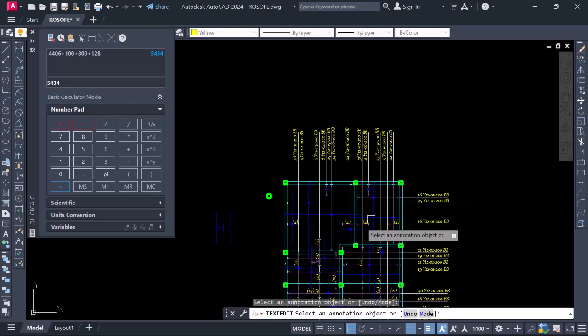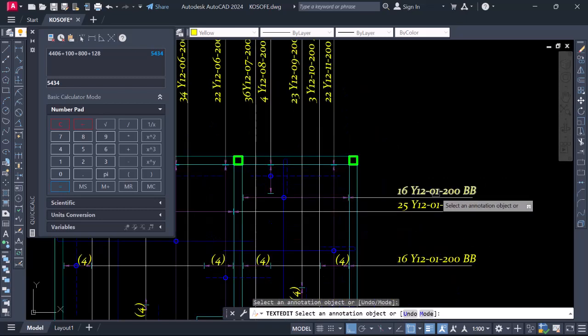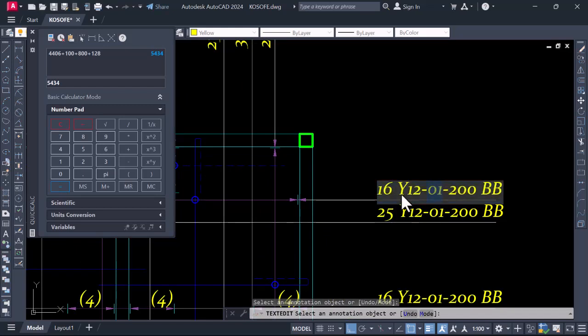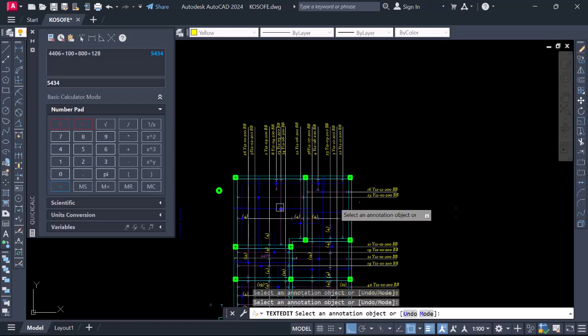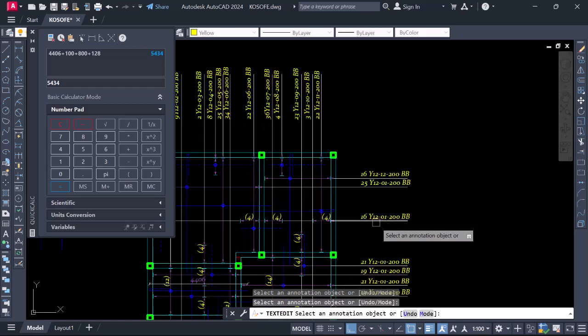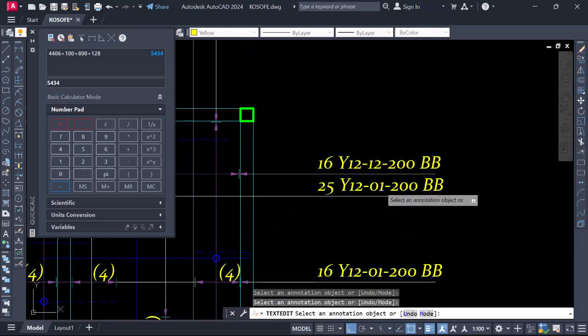Okay, so we'll do the same to this. This is going to be bar 12, right? And the next one, they have different. You can see this is running from here down to this span, while this extends down here. So they have different length, all right? Though they have the same size of the bar and the same shape, they have different length. So currently we're looking at length while talking about this. So this will be a different length. This will be 13, right?